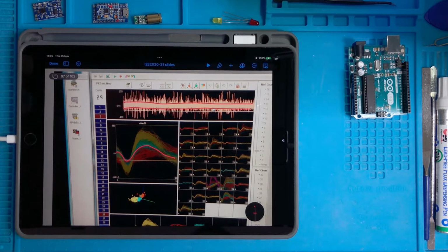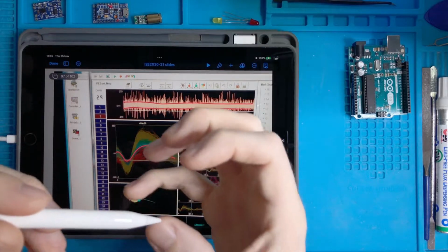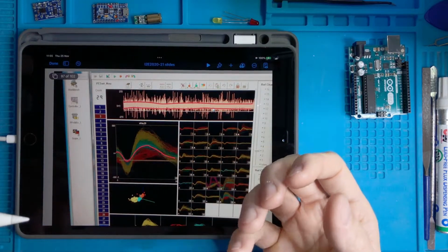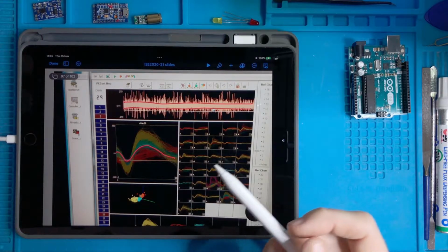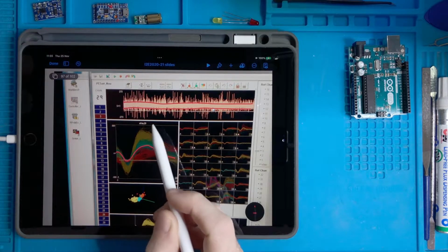Ideally you would like to have an impedance of an electrode which is so much tuned that it records only from one neuron. But then you might have the risk of putting the electrode in a place where there are no neurons, and if you make this capturing area so small, then maybe you will not capture anything. So it's always a compromise. And there are mathematical methods to try to isolate a neuron. The simplest one is, for instance, to look at the peak amplitude.